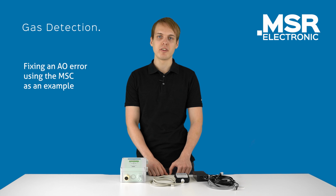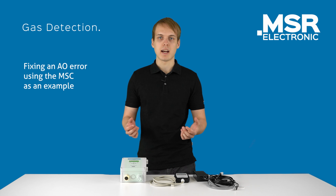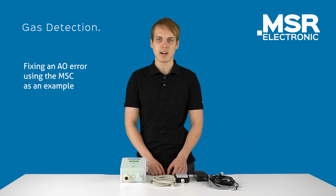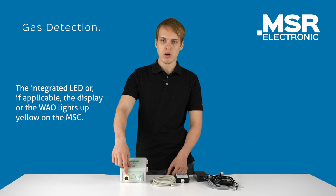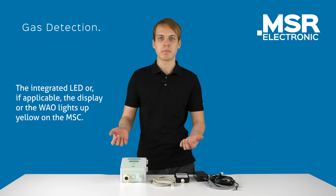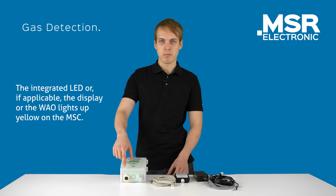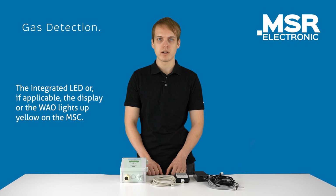And today I show you how you can fix an analog output error using our gas warning device, the MSC tool. But how do you notice an analog output error? You will either see the WAO or the integrated LED of the display light up yellow. If you don't have both of them, then the integrated LED on the board will light up yellow.